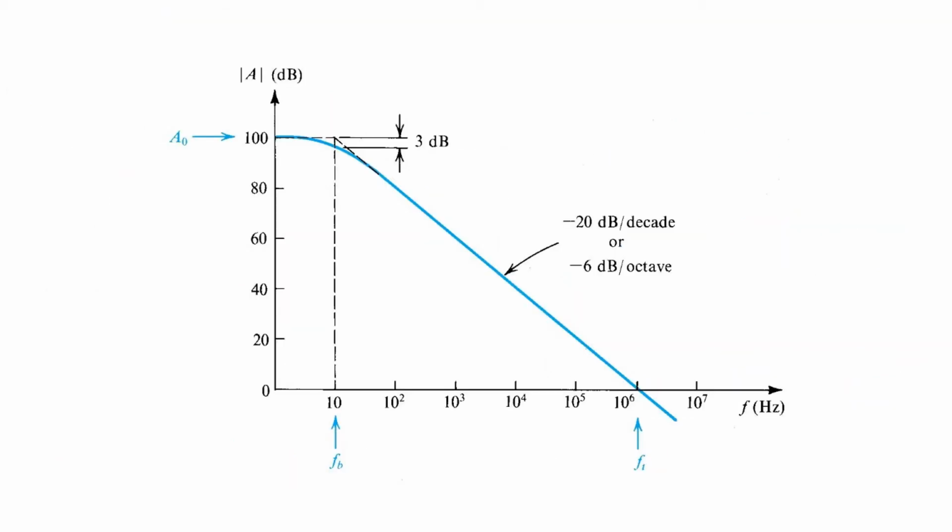I think it's interesting at this time to think about what happens when we have an op-amp whose gain A is a function of frequency F. For example, following the plot shown here. And we just showed that in an inverting configuration, as long as the amplifier gain A is a lot larger than 1 plus R2 over R1, then the closed loop gain of the inverting configuration will be closely approximated by the ideal result of negative R2 over R1.